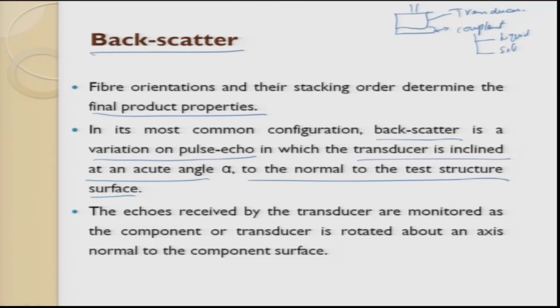When I have a solid, I can give it shape. The moment I give shape, I try to make something called a shoe, and this shoe can be made at any angle in order to make sure that I get this acute angle alpha. Once I have this acute angle alpha, I can quickly figure out the stacking sequence which you have used in the composite.